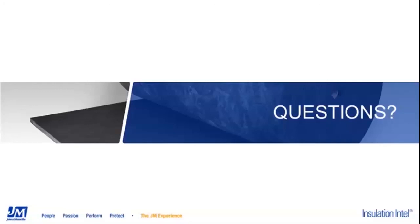All right, thank you. So, a similar question. When we compare mineral wool and fiberglass for HVAC equipment installation for thermals, which one is better? Josh, we'll start with you. In general, the fiberglass I believe is going to be a little bit better, but you're going to have to discuss what different thickness you are looking at, or what different density.